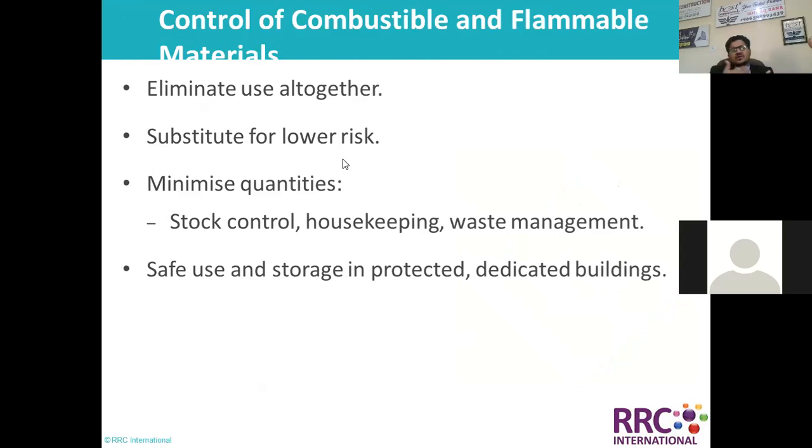There is always a lot of research going on, so we just need to keep updated through regulatory bodies and see if something has been invented and is available in the market as a substitute. Instead of high risk liquids, why can't we substitute with low risk? If solvent-based paint is extremely flammable, why can't we use water-based? In the same way, we can minimize quantities, through stock control, housekeeping, and waste management.